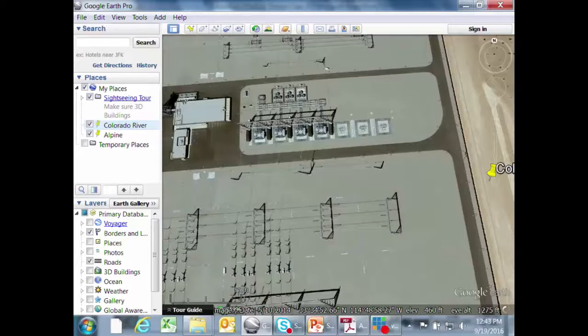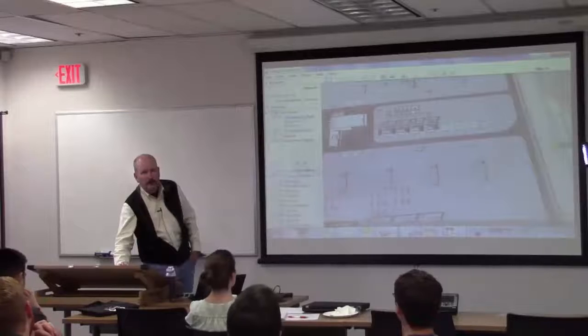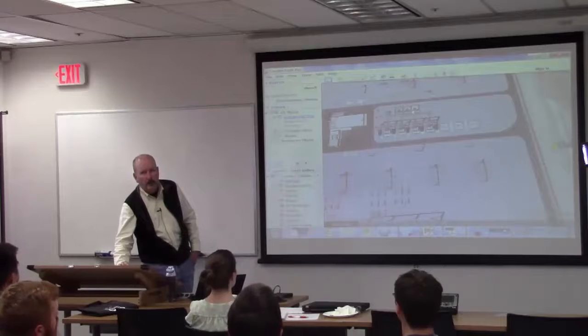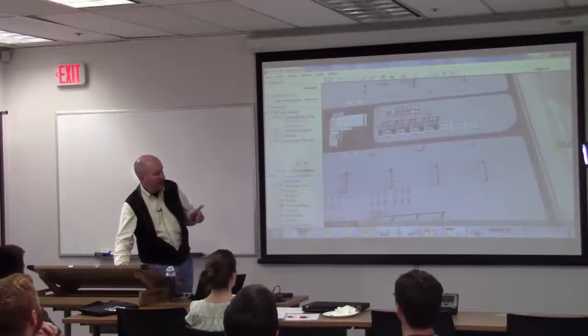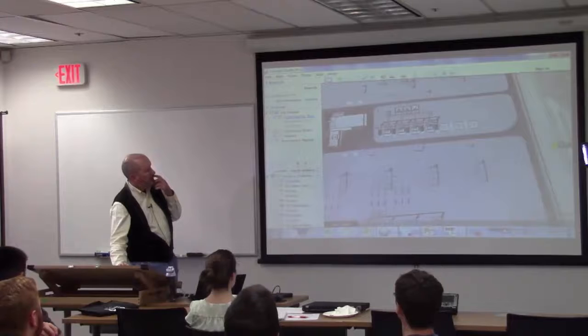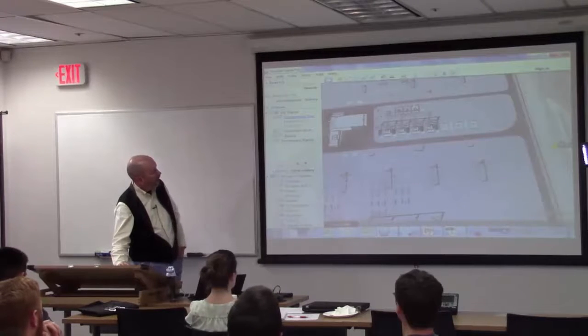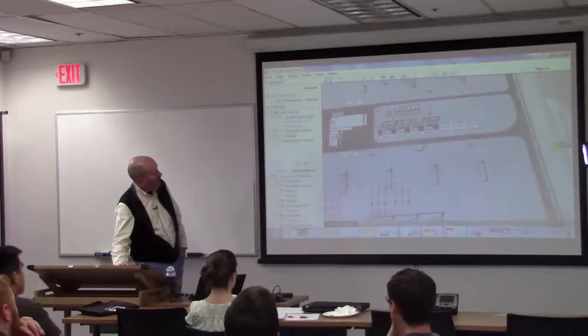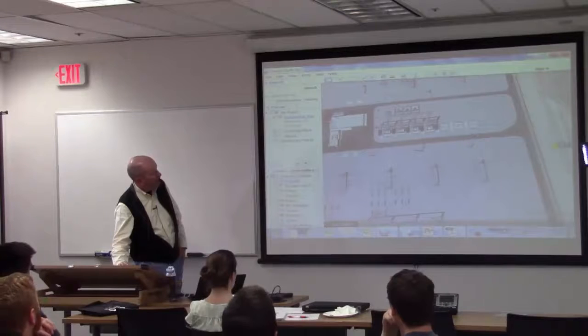Those are nice big slab foundations, but these are an interesting beast because they have a huge magnetic field associated with them. So you either don't use steel rebar, or you have to be very cautious in how you do it, because you can't have any closed loops. Anyway, the last feature of this is a jack bus, and this thing facilitates being able to take one of these transformers out of service and connect this spare in its place.